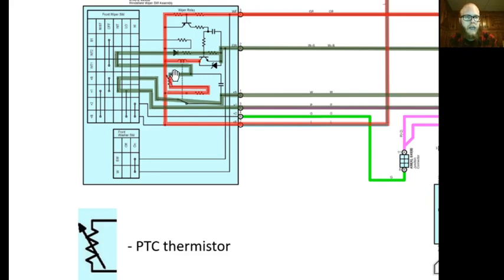Well, let's take a step back. This is supplied power all the time, but it is not supplied ground all the time. Okay, you see that the resistance here has to decrease to a certain point at which it will allow enough voltage and current to bias this. And the way that that happens is this has to cool down. And the only way this is going to cool down is with a little bit of time of no current flowing through it. So it wipes, it nudges it, it gets warm.